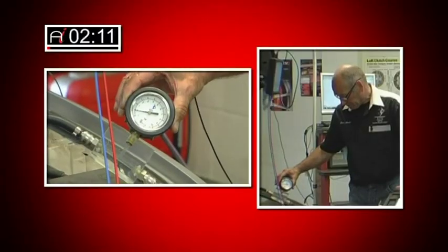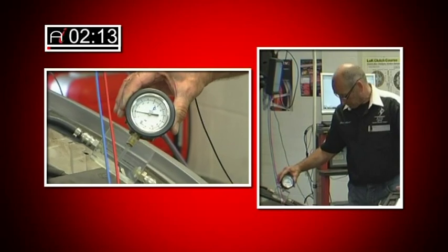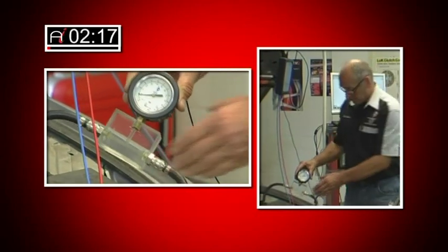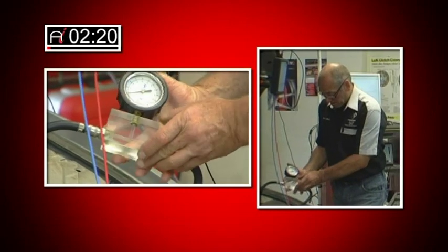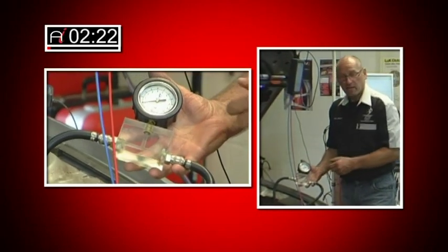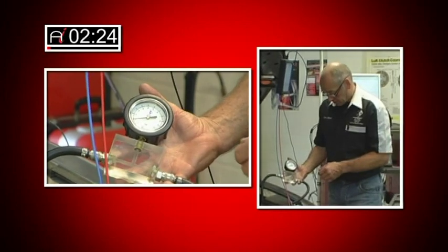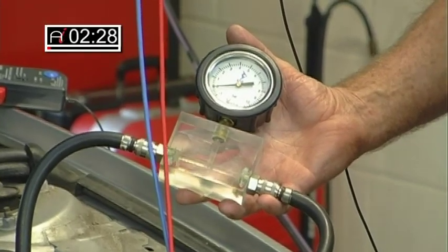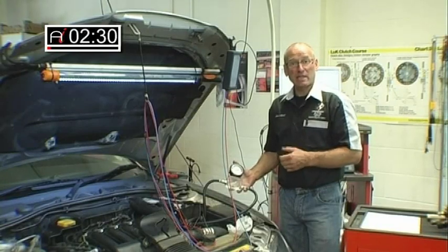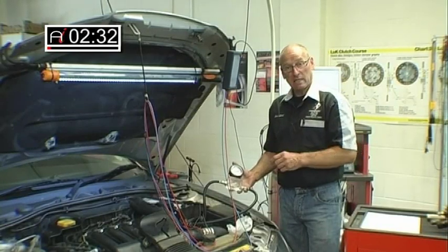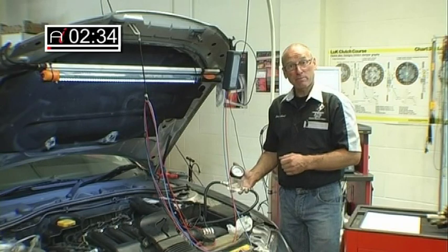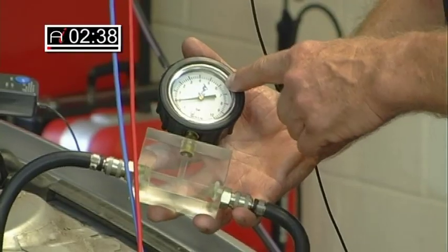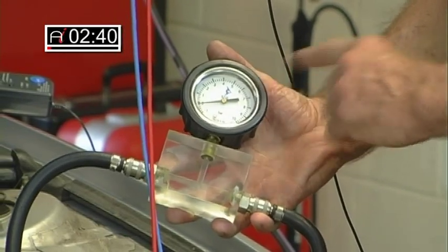I've attached the low pressure priming gauge, and we've certainly used this gauge many times before. The advantages of this gauge are that we take direct pressure measurement. In our case, this particular system uses a positive supply system. In other words, there is a positive supply electric pump fitted to the vehicle which provides positive priming pressure to the high pressure common rail pump. So we can read directly off the gauge positive pressure.